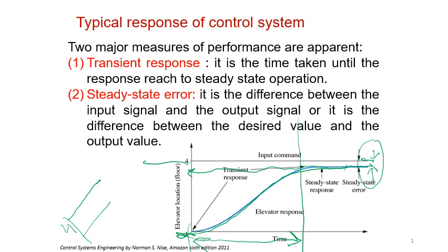The transient time and the steady state error are not values to be fixed for any system. No, every system has its own properties. So for example, in the lift, the transient is not advisable to be very short and not advisable to be very long. We want it to be something acceptable by the human. And even the steady state error, a very big steady state error is not advisable. A very small steady state error is no problem. It's going to be good.